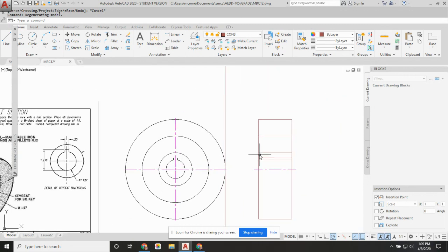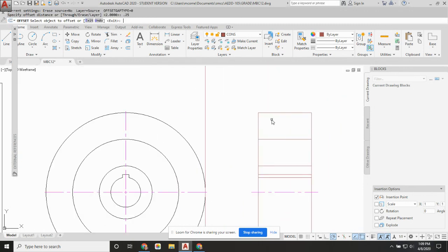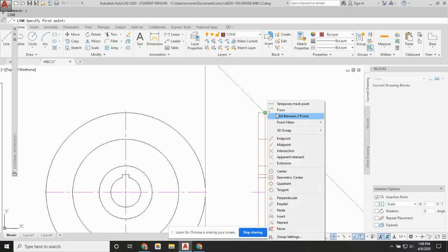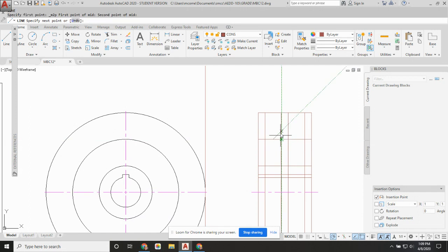So if we take our dimensions by, first of all, creating the pattern that's indicated by offsetting, we don't care what that dimension ends up being, that's a resulting dimension. This has to be 0.25 and this has to be 0.62, and we're doing the same thing from the other direction. Right here, these 2 points that we found are where the ends of those angled lines are going to be that have an angle of 40 degrees. So if I were to draw a line that is the midpoint between these 2 intersections straight up, that's at a 90-degree angle.